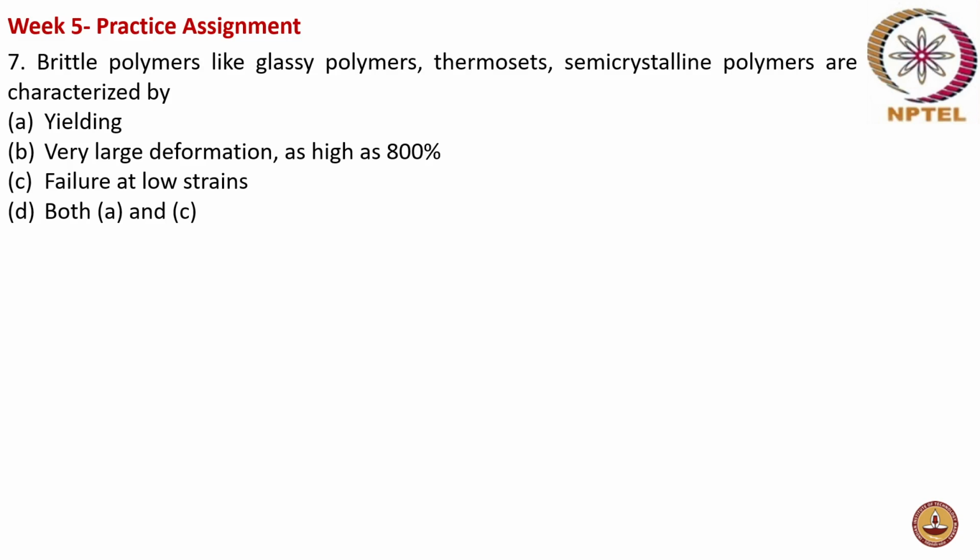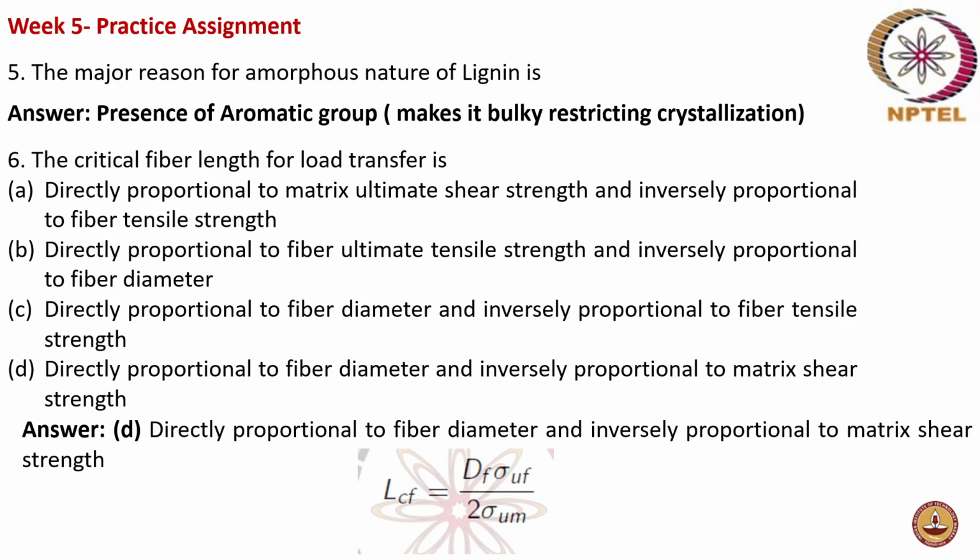Excuse me, I have some doubt on the last question. Tell me. See, even if we see that shear strength is almost proportional to tensile strength, we can say C is also equally correct. Shear strength? See, here when it comes to composite with fiber, in terms of fiber, you say it as tensile strength. In terms of the matrix, you say it as shear strength. When you apply a shear, the matrix takes it as a shear, whereas the fiber elongates and takes it as tensile elongation.